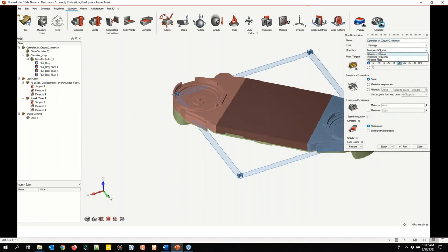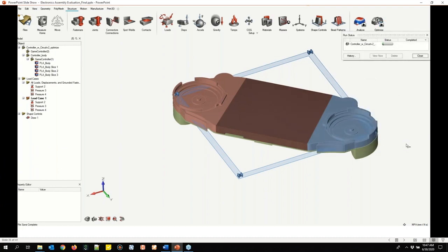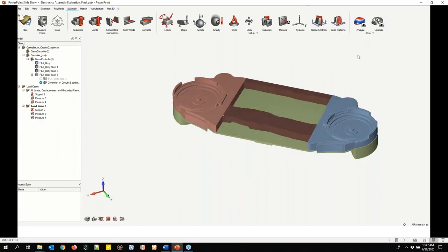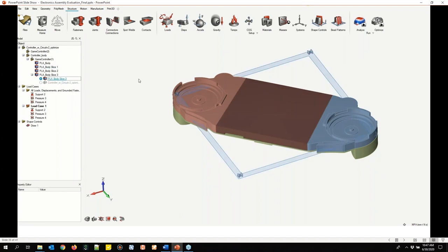My optimization setup is going to be to maximize the stiffness, and I'm going to set a constraint to basically reduce 70% of the pre-existing material of where that design space is. So basically, again, I'm telling the tool I want to maximize my stiffness, but I want to remove as much material out of this design space as possible. And I did that with an extrusion constraint. So basically, that's ensuring that whatever design concept is generated is extrudable.